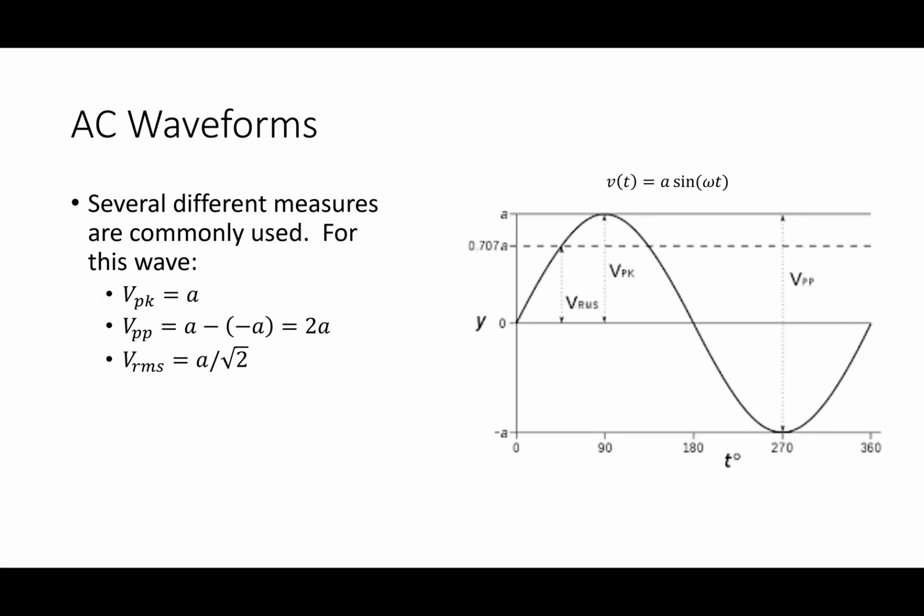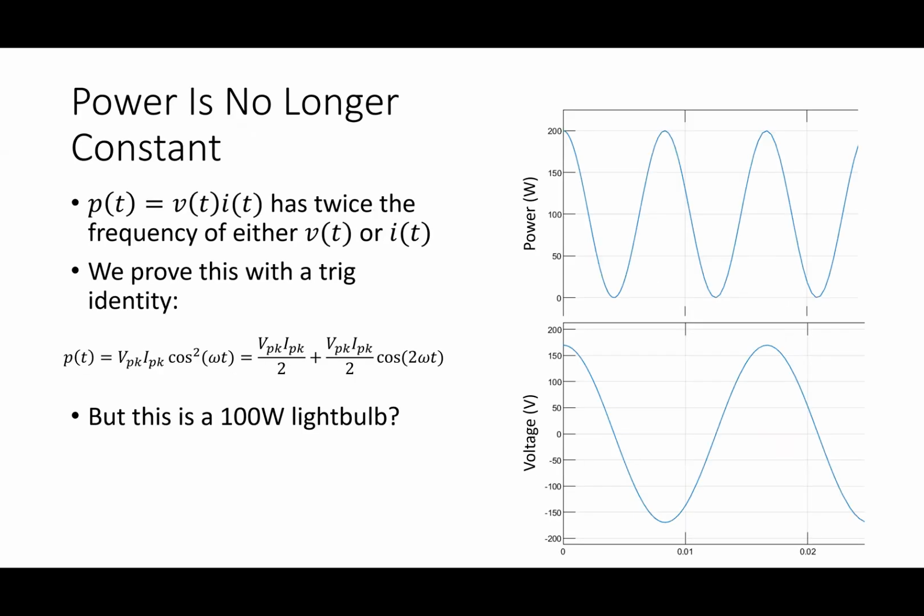So we're going to use RMS. From this point forward, everything is going to be in terms of RMS, because it's easiest to do that with power. That is actually the most common thing to do. If you go into the lab and you use the multimeter, usually if you put that meter so that it measures AC voltage or AC current, it's measuring RMS. That's the number that it tells you when you're measuring an AC waveform. So it's very common that we use that. Engineers always use the RMS number.